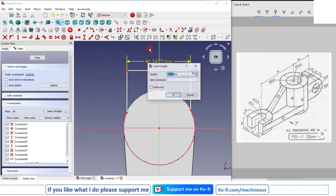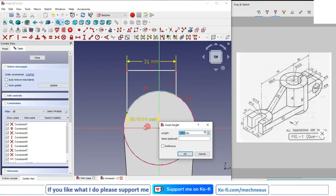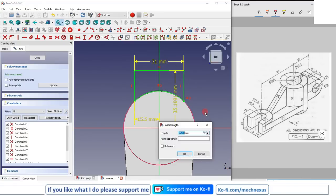I will give the horizontal dimension of 13 plus 13 plus 5, it is 31. Now I will select this point and give 31 divided by 2. So we can see that the center to center distance is 35 plus this radius is 15, so it will be 50. So I will select the dimension, and from here to here I will give 50 mm.